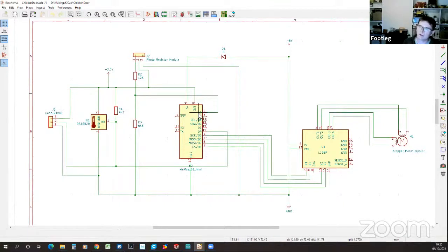So 6 volts would damage it, but just by putting the diode in there, it drops the voltage with a cheap as chips component, and it also gives me polarity protection. So if I ever accidentally connect things up the wrong way, the diode will stop the electricity running the wrong way through the board and damaging it. So two for the price of one feature there.